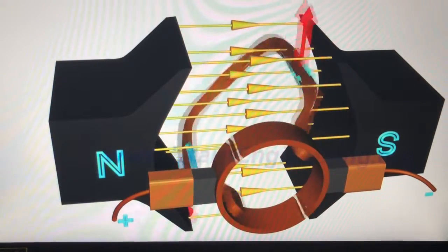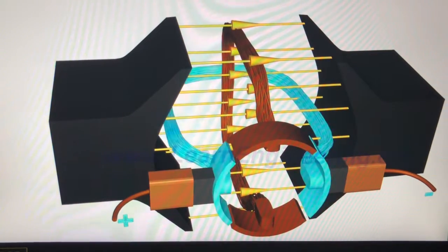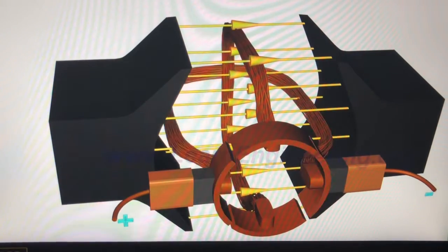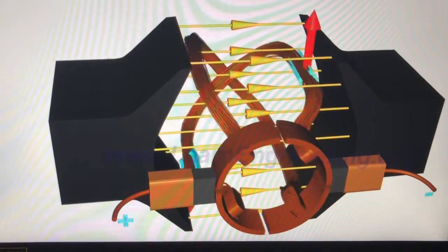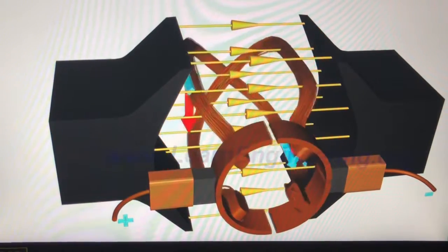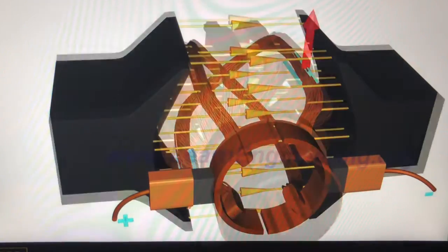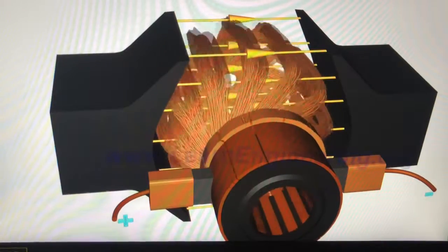Here is the trick to overcome this problem. Add one more loop to the rotor with a separate commutator pair for it. In this arrangement, when the first loop is in the vertical position, the second loop will be connected to the power source, so the motor force is always present in the system. Moreover, the more such loops, the smoother the motor rotation.